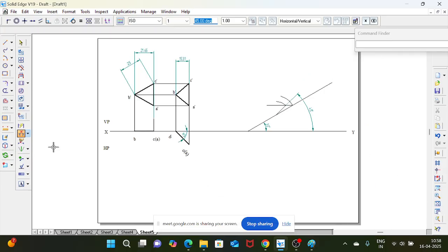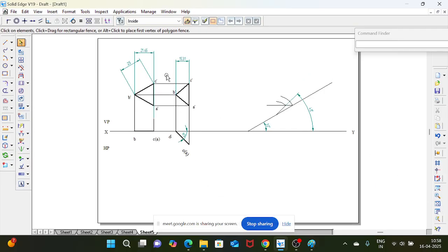Now you have to place your second position front view, picking from the B point. You have to place it on the arc center. To get the arc center, you have to move your cursor on any arc. The arc center will highlight. Your B point has to be placed on the arc center like this.